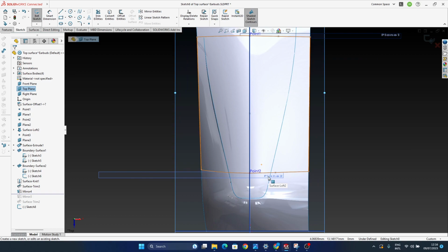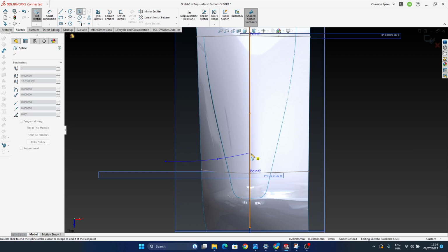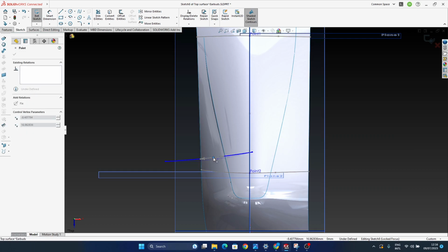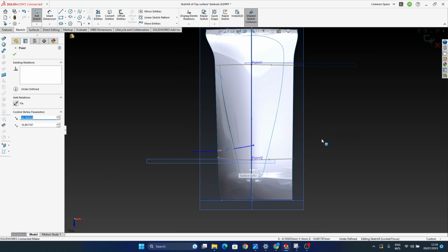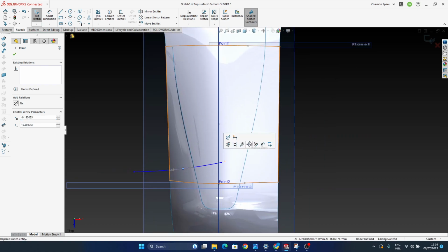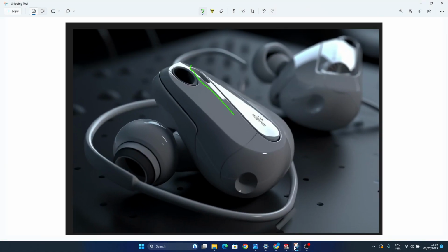So what we can do is cut using curves, but that will go into straight corners. Use those surfaces to adjust, and then trim them to create some sort of fillets, and then use those for blending, right? Let's try to do exactly that.